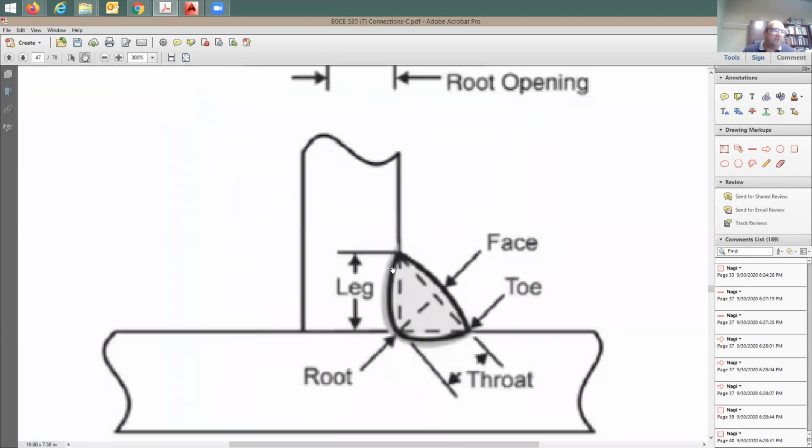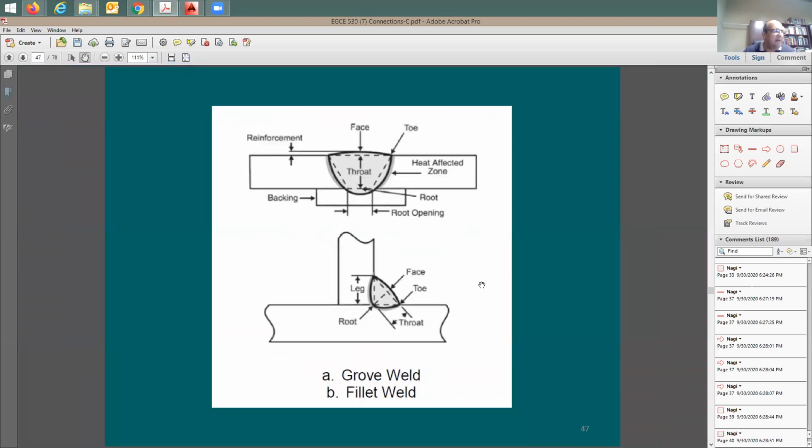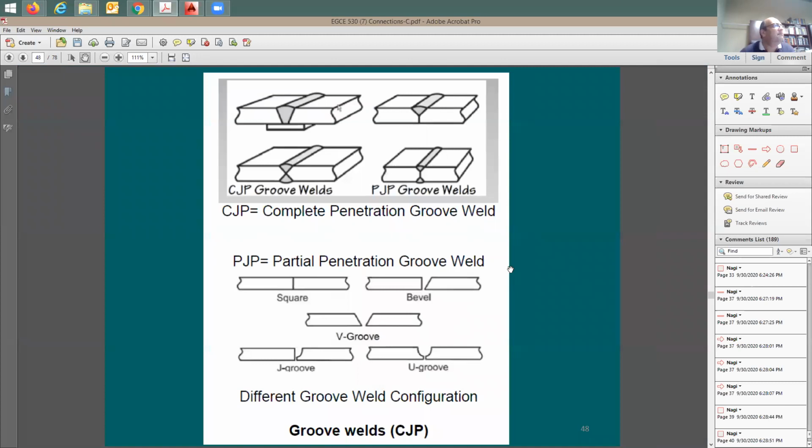You see here that it usually takes a little piece of the metal itself because of the fusion effect. You're going to be heating the steel plate or the steel material so that you provide a full connection between the weld material and the steel metal itself. As you see here, this is what they call complete penetration or complete joint penetration. We call this CP, complete penetration.